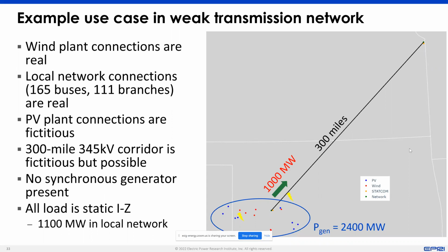But in this case, we had all the frequency control here, while for voltage control you need to have it on both sides, because there's only so much. Even if you have a long transmission line, there's some amount of charging current provided by the line that gives maybe some voltage rise. But after a point, there's only so much that it can do.